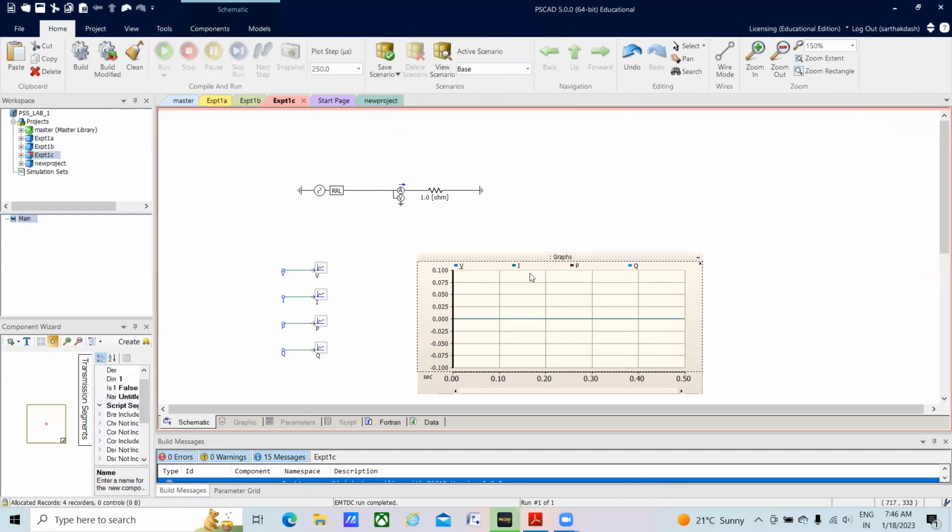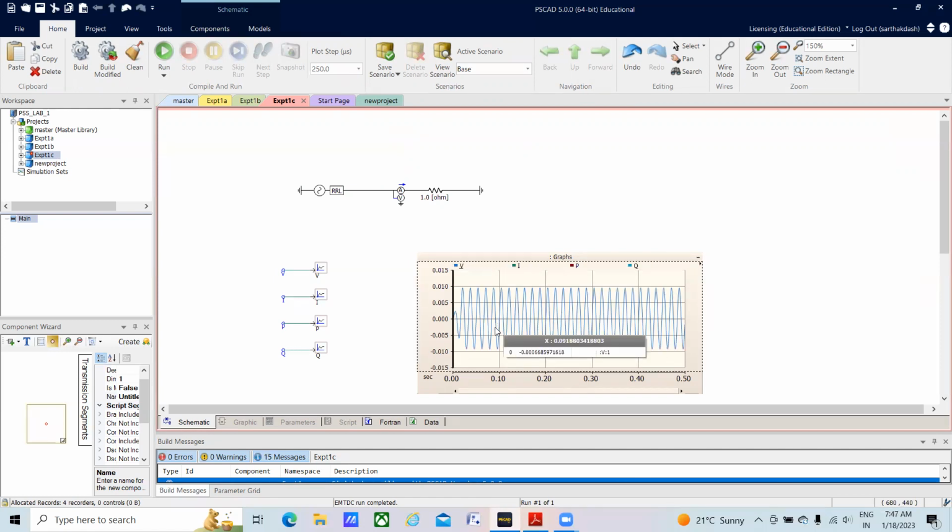See what I'm doing is, now every signal I've made will not be plotted here. Then I want to see my voltage signal, so you have to just click yes for the view, and then press here and click Y, so that it will be auto scaled.